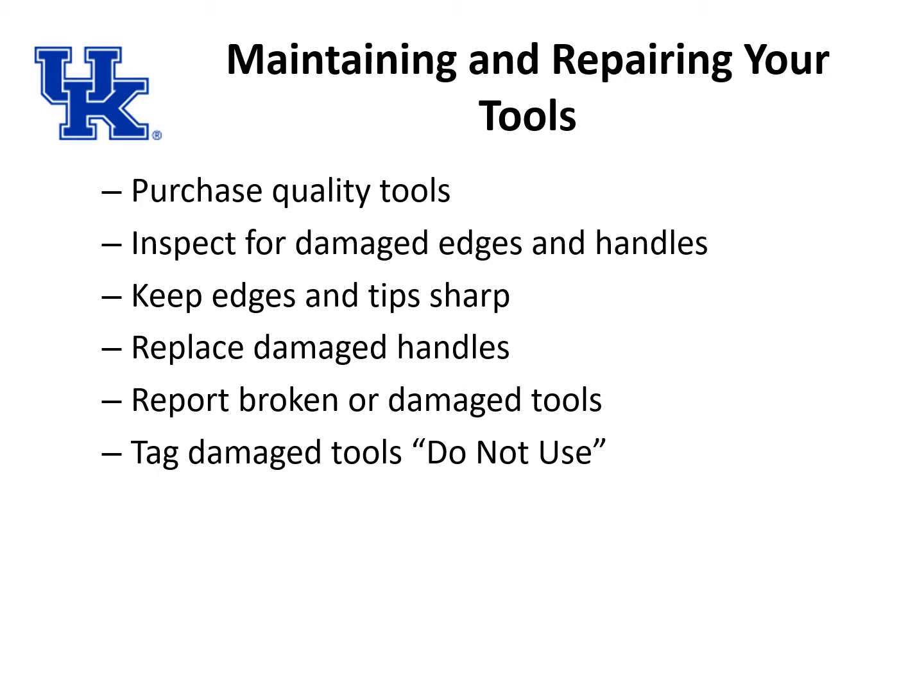Have a professional sharpen edges or tips of the tool and blades. Replace damaged handles or grips immediately. If a tool breaks or malfunctions, report it to your supervisor. Mark or tag damaged tools with "Do Not Use" in order to prevent a coworker from using the tool and getting injured.